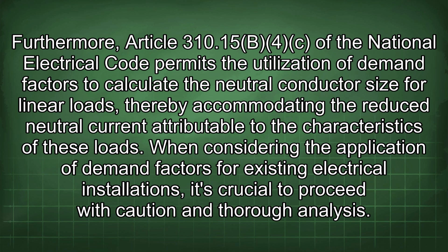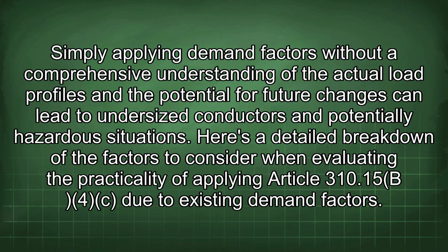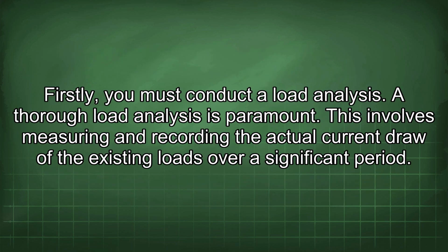When considering the application of demand factors for existing electrical installations, it's crucial to proceed with caution and thorough analysis. Simply applying demand factors without a comprehensive understanding of the actual load profiles and the potential for future changes can lead to undersized conductors and potentially hazardous situations. Here's a detailed breakdown of the factors to consider when evaluating the practicality of applying Article 310.15(B) due to existing demand factors. Firstly, you must conduct a load analysis.